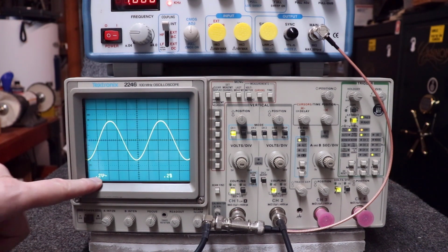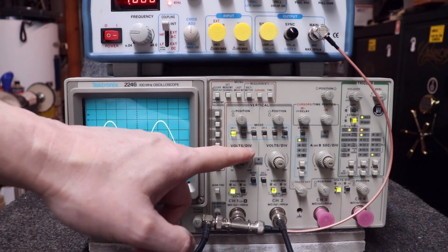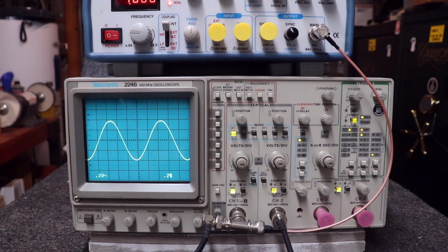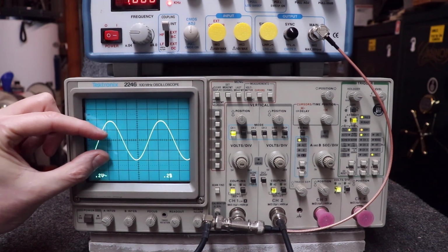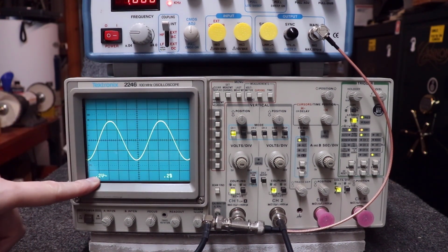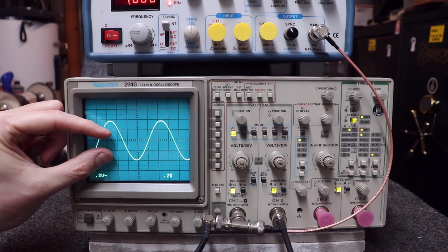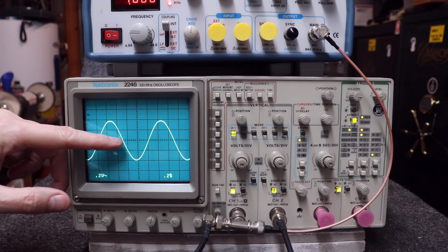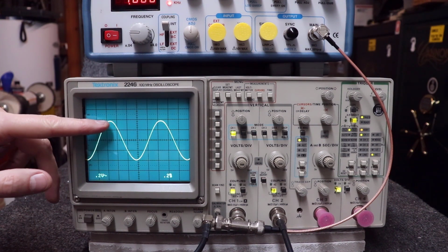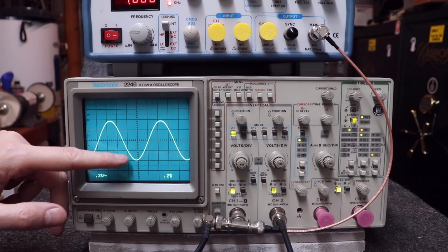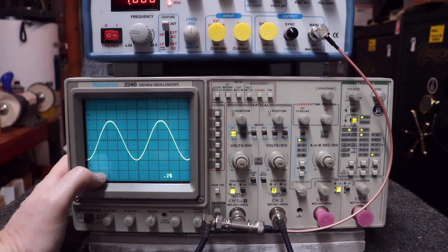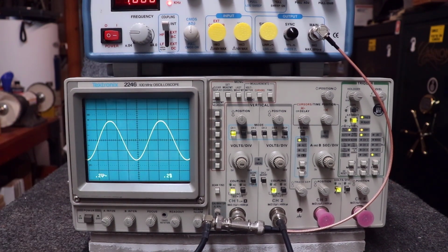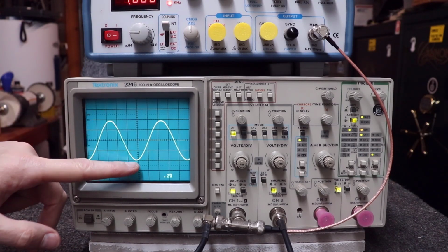Okay, up next we have something here titled readout. Now, this oscilloscope happens to have a readout that shows you what the settings are for the horizontal and the vertical. So what this is telling me is that each of these little gradients right here is 0.2 volts per little box. So if I looked at this signal, I would say 1, 2 boxes going this direction, 1, 2 boxes coming down. So that signal total would be 0.2 times 4, or 0.8 volts peak to peak here.